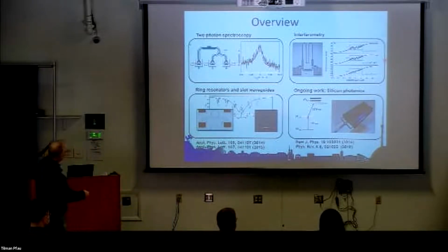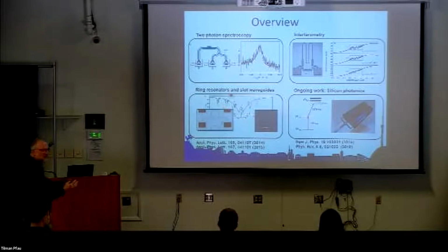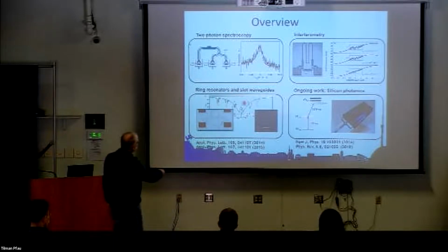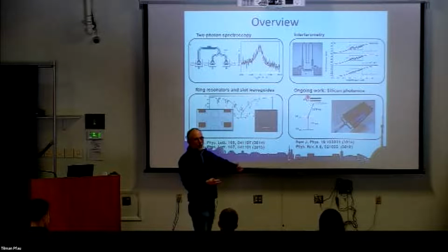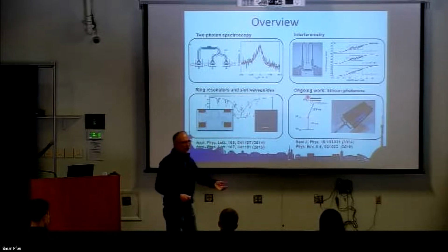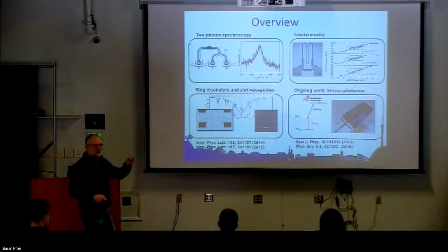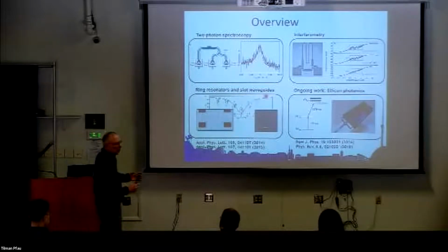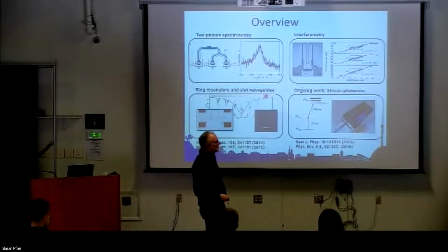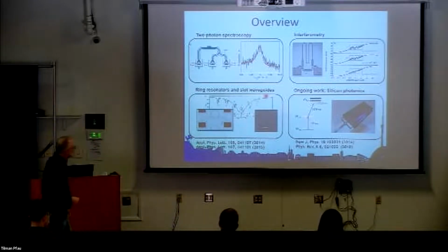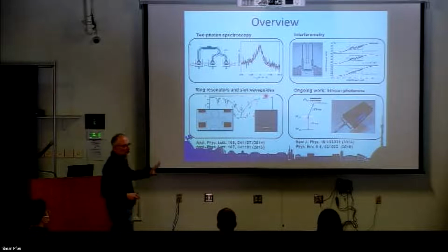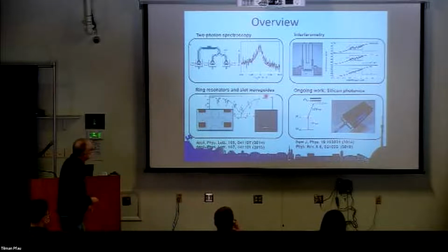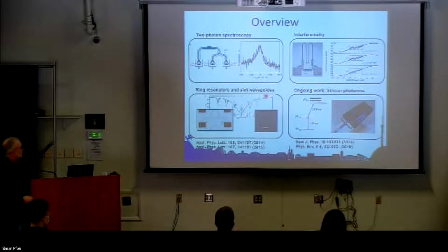Okay. You can make ring resonators here. A ring resonator is an optical resonator that has a resonance line width. It's actually this broad feature here. And on top of that broad resonance of the optical resonator, you can now look at the more narrow resonance of your atomic medium, and you see that these atomic features here can be shifted around if you tune the resonance frequency of your resonator, for example, by the temperature. So these are just examples of, let's say, absorption or dispersion, just linear optics effects of this atomic media in a photonic circuit.